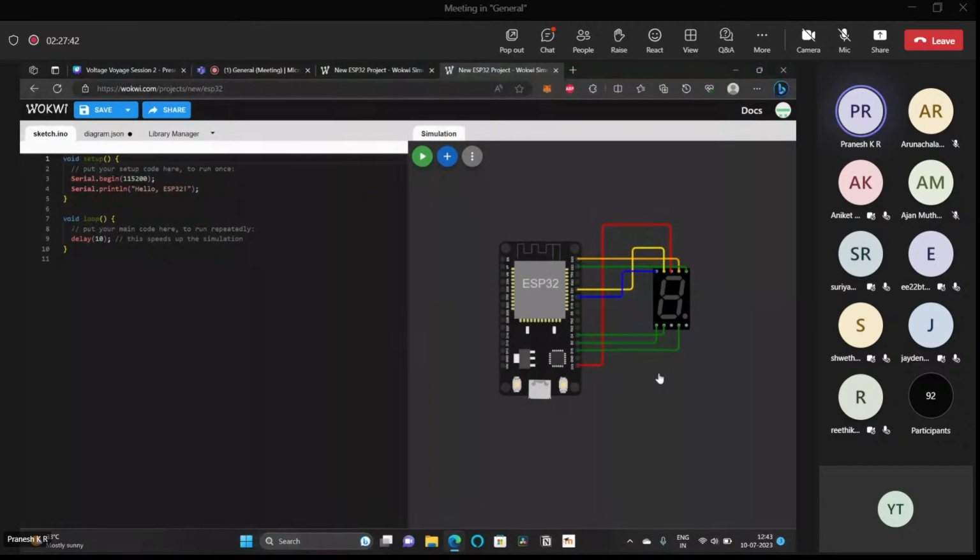Now we have connected all 7 segments and we will not be using this decimal point again. So leave it. And this common also we won't be using. Or else you can remove this anode and connect the other side to anode to VCC. That is also fine. Now again, if you guys are done with this, give some thumbs up so we can go to the coding part.